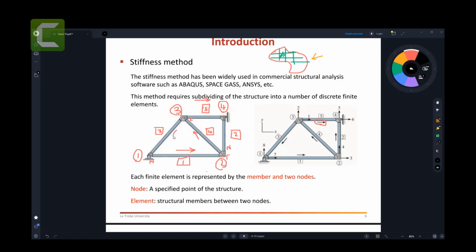Now, if I put the arrow going in these ones, for member number 3, there are 2 nodes, which is node number 3 and node number 1. Which one is near node and which one is far node for member number 3? If I put the location vector here, yep, 3 is near, correct, and 1 is far node. That is correct. Again, location vectors do not matter. You can put the arrow the way you like. Your answer will not be changed. But the rule is you must have those arrows in place when you do it.